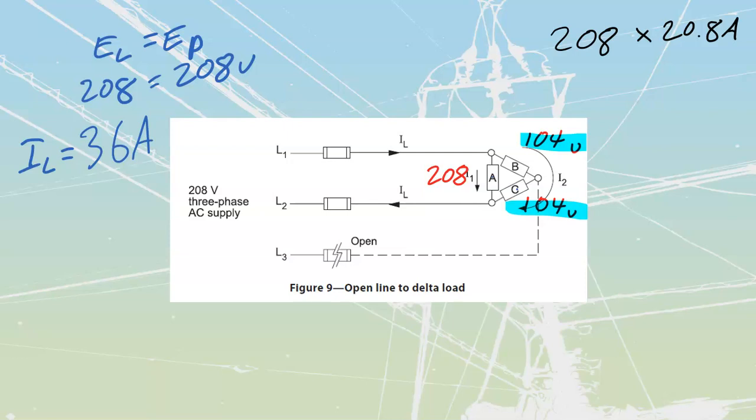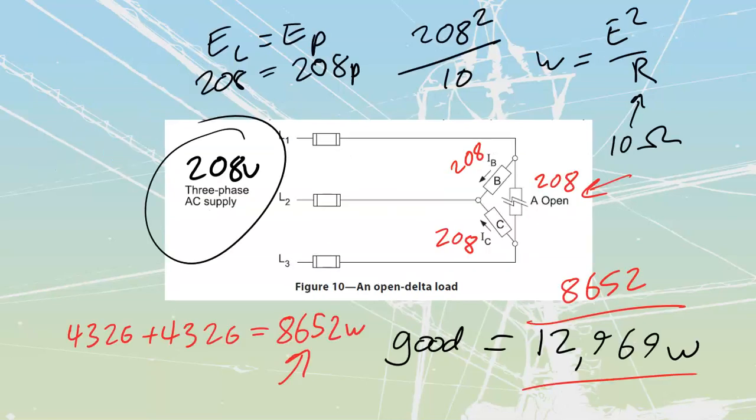If I've got a delta load, and I have got 2 small voltages and 1 larger voltage, that's got to be an open line. If I have got a delta system that's not putting out full heat, you know, that's what the customer is going to be telling you, but I've got proper voltage over top of every single element, that means that I have got a dead element that's going to be somewhere inside of the mix. Okay, that's that for your open delta calculations.